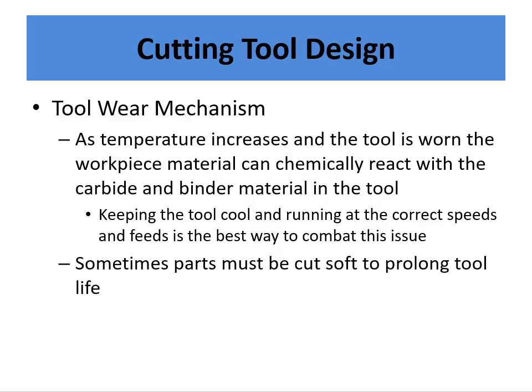In general, I would say from a manufacturing standpoint, you generally don't want to heat treat after you cut things because you lose dimensional stability, but sometimes they have to be cut. Although today, what used to be considered too hard to cut years ago can be cut. Nowadays you could machine 45 Rockwell or 50 Rockwell parts, whereas years ago that was not a thing. You couldn't really do that. But there may be a case where you want your parts softer to prolong your tool life.